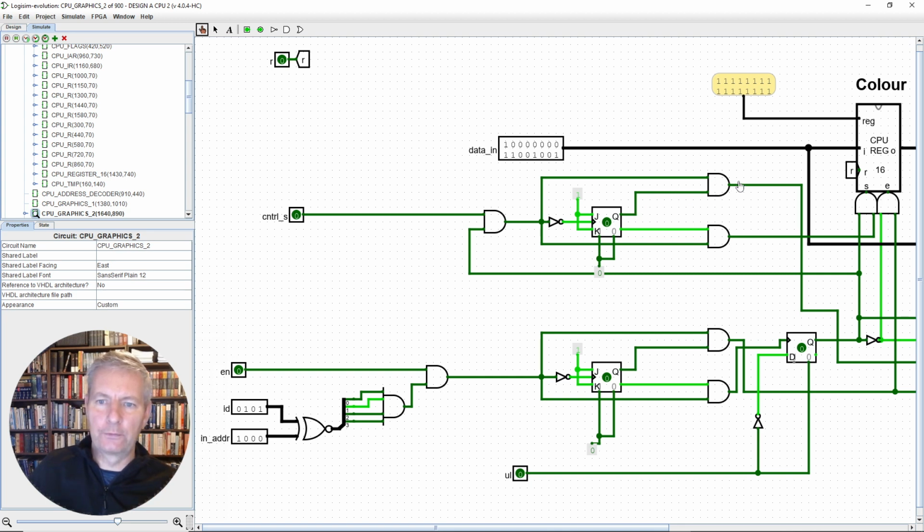So it meant that these values here at the output of this JK flip-flop were pulsing randomly as we ran the code. And we didn't actually want that, because it meant that whenever we actually pulsed this value here, when we did want to use it, then this would be sitting in some random position. So what I had to do was take the output from a certain point.